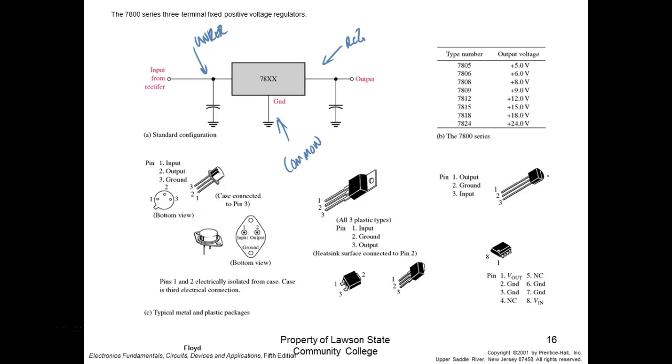And then we have variable regulators, which are 3-terminal regulators. The way they work is they'll come in and we'll put 2 resistors right here. Then this right here will be variable, and your common lead connects right there. And these are variable regulators. We'll look at them. So this is what the trainer uses.